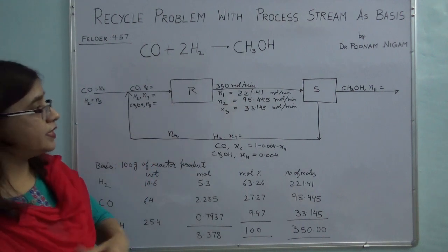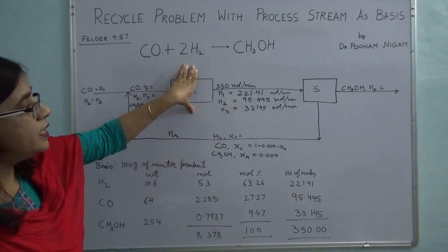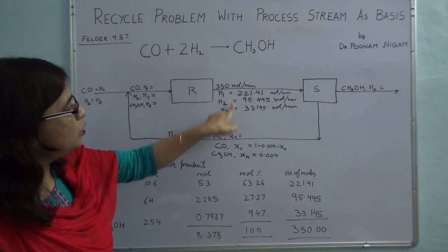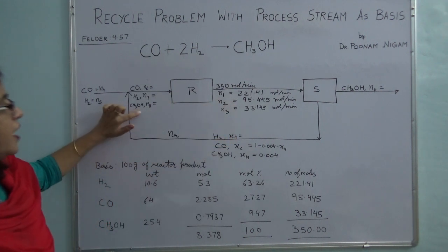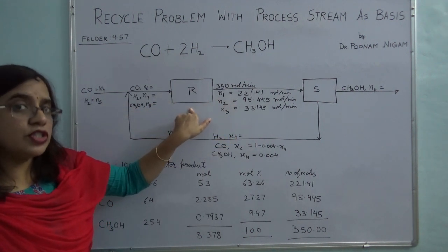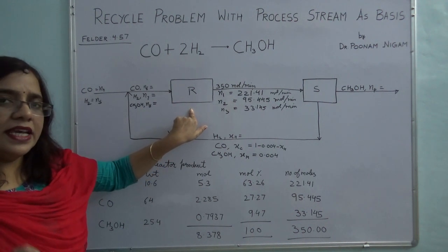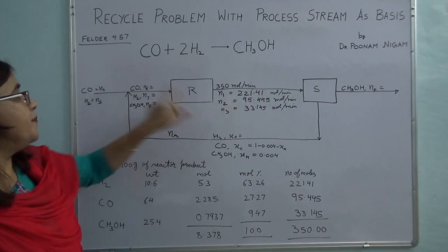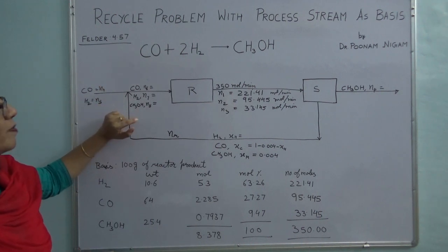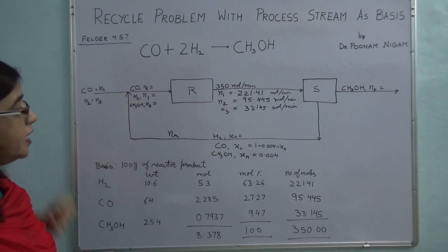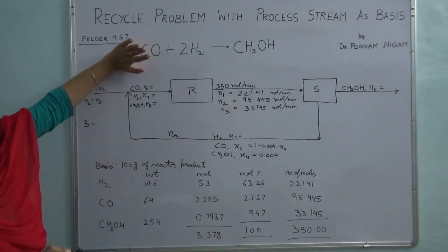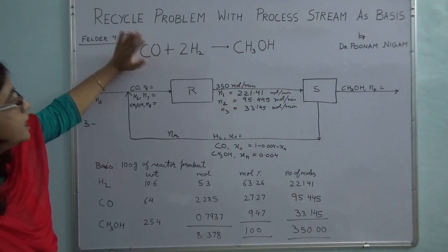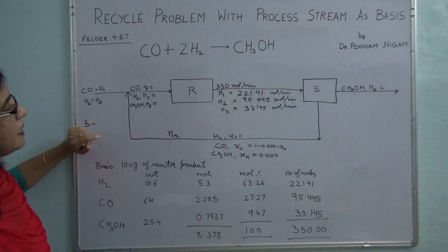So now what I will do is, let me check on the reactor now, because I know all these effluent stream compositions. So you might think, let's try over here because there is a reactor which is involved in this. Let's go directly and take atomic species balance. If I take atomic species balance, how many variables do I have? 1, 2 and 3. So I have 3 variables. Reaction we are not going to count because this is atomic species balance.